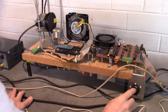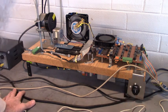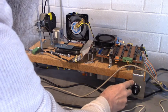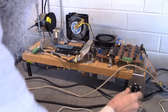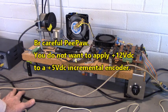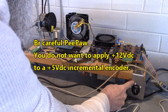This selector switch right here selects the 3 different voltages of encoders that I normally work on. There'll be 5-volt encoders, 12-volt encoders, or 24-volt encoders. So this knob right here, I can rotate it to the voltage required to power up that encoder. This encoder that we're testing is a 12-volt encoder.